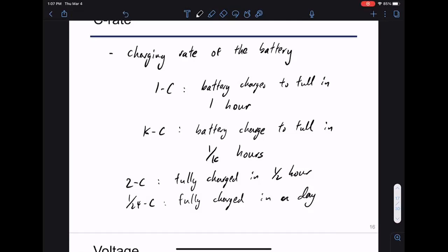The safety characteristic is hard-coded into the battery management system. For example, you take your phone, there is an upper limit to the C rate it will charge at. You cannot actually get it to charge faster than that. It's very difficult. There's a management system sitting outside the battery limiting how fast you can charge.